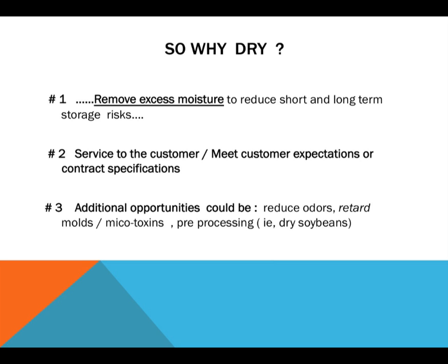I managed facilities where we would regularly dry corn out of the dryers and shove it into steel tanks with good air at 18 to 20% moisture. Okay? Now, you have good cooling and you can get it cooled down. You can maintain it for a long time. But you're not going to shove 20% moisture corn hot out of the dryer and put it into a bin that has marginal aeration and hope to have any success with that.